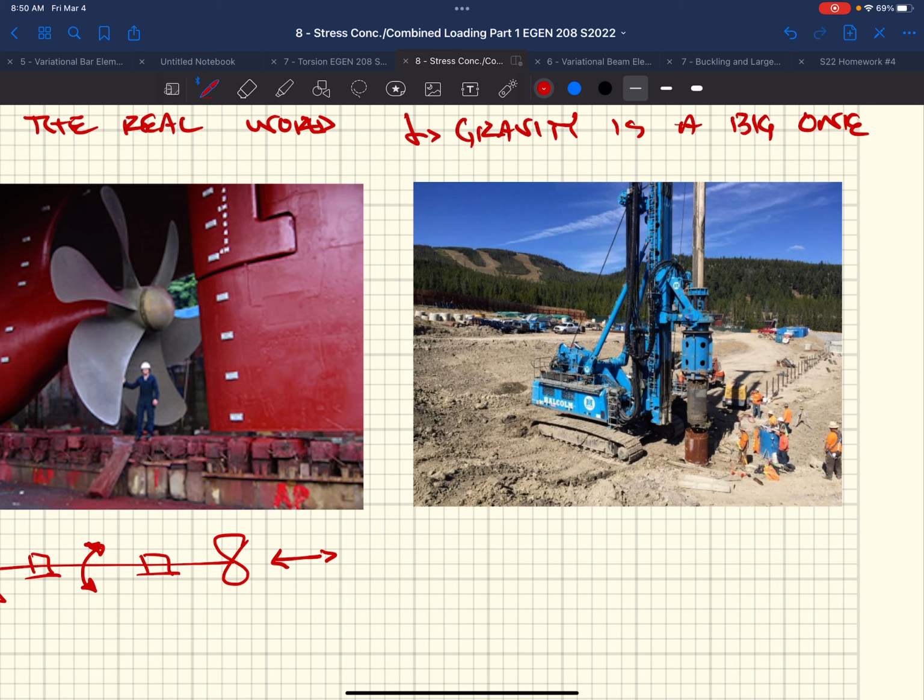The engineering company that I used to work for had surveyors who would go up there once a week. They had a bunch of prisms out on the wall, and they would essentially have a robotic total station that would just go boom, boom, boom, shooting all the stations. They could start mapping how fast or how slow this mountain was falling down the hill. They put millions and millions of dollars into it.